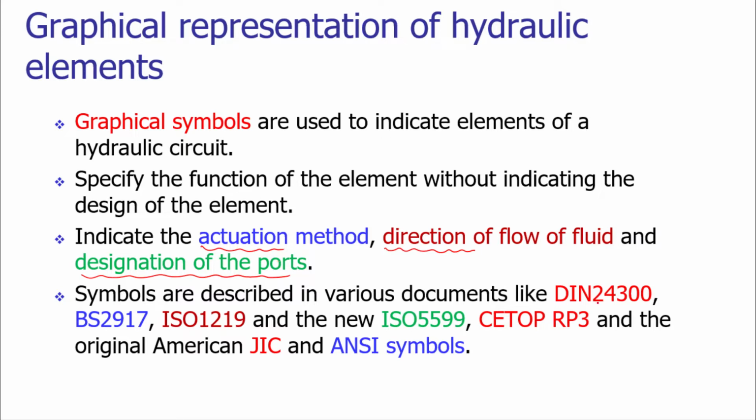and these guidelines can be seen on your screen. These are DIN 24300, BS 2917, ISO 1219. The newer standard is ISO 5599, and many such standards are available.